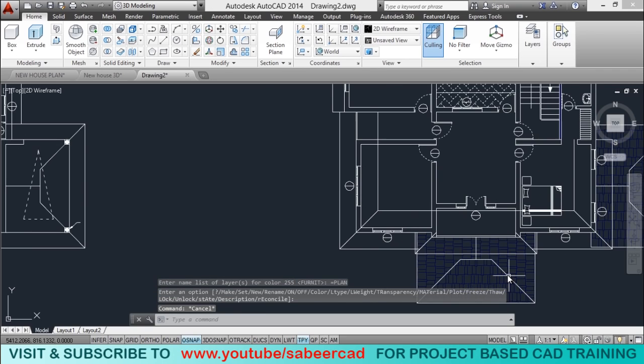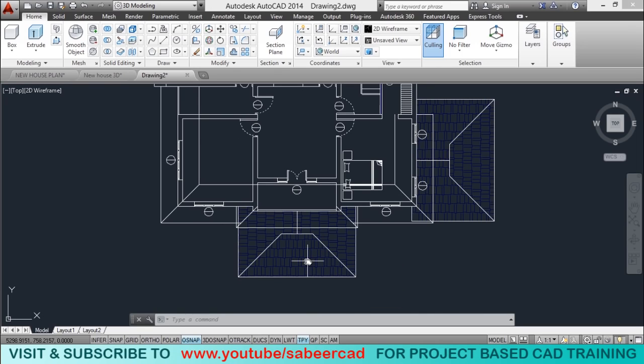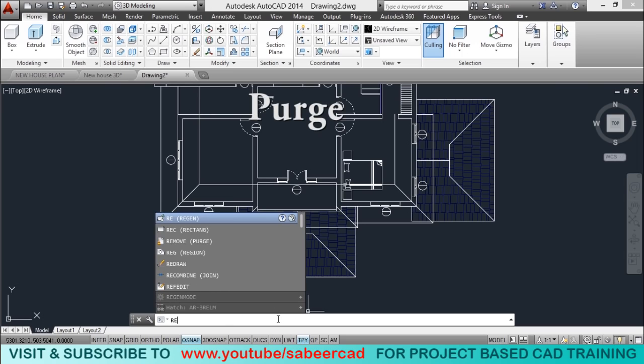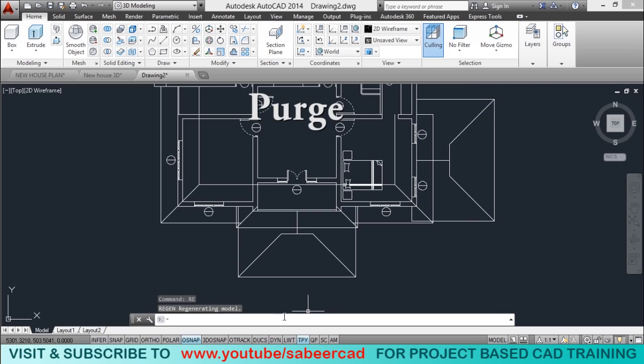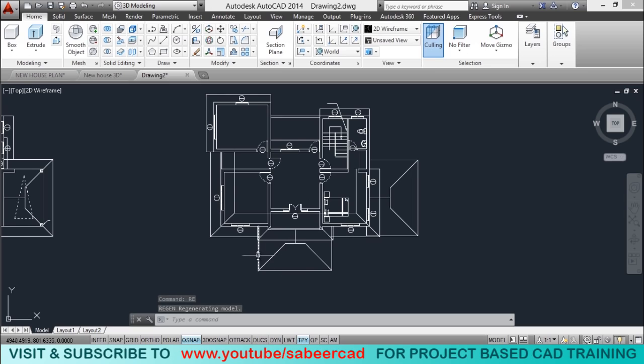Now these objects are hatch objects. In AutoCAD, if you want, you can temporarily suppress the display of hatch objects. It is done using the fill command. So I'll type the letter fill. Then you can just turn off the fill. So type off. Then you can give a regenerate command. So type RE. RE is the abbreviation for regeneration. Now the display of hatch patterns got suppressed temporarily.